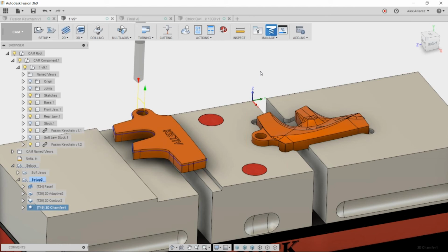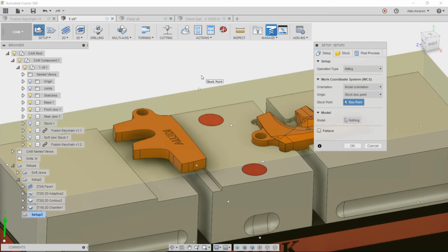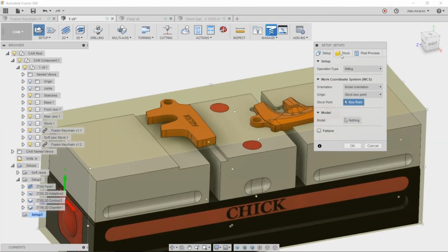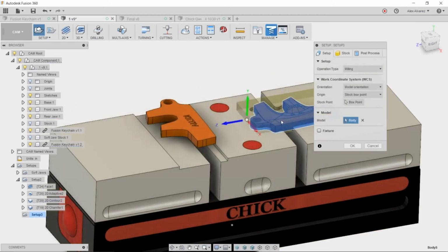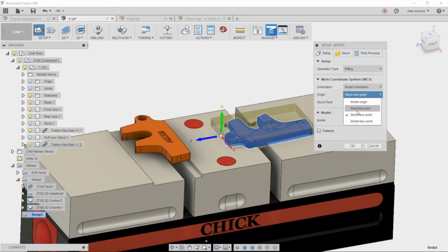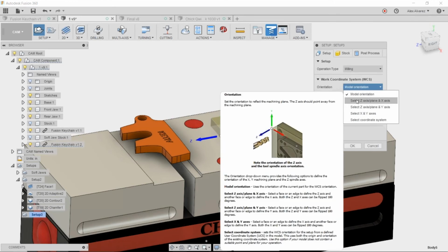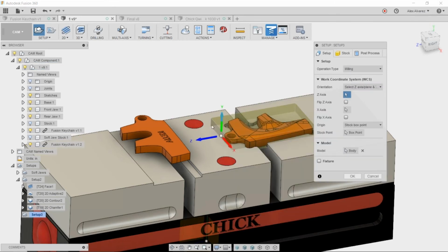What I like to do with those is usually start off with the toolpath and do nothing but select the tool and then click OK, and see what the toolpath gives me. With that, you always run the risk of having a funky looking toolpath. But then I go into the options and start checking off a few of them, trying to contain the toolpath that way.